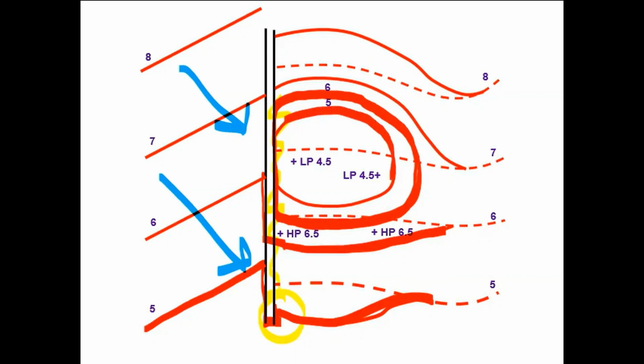And this 5 is actually running around, and it's going on the back side of the curb and connecting into itself. So what that means is that in this area where we have the bioretention system right next to the curb, the depth of the bioretention system is further down on the back side of the curb than the asphalt is on the front side of the curb. In fact, in this case, it's about a 2-foot drop. So we'd have about 2 feet of the back of the curb exposed to the bioretention system. So for all intents and purposes, that curb becomes a retaining wall.